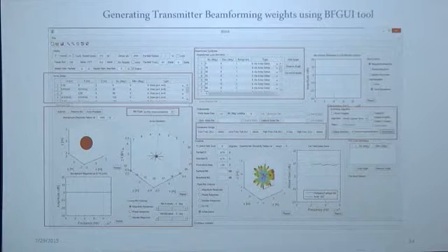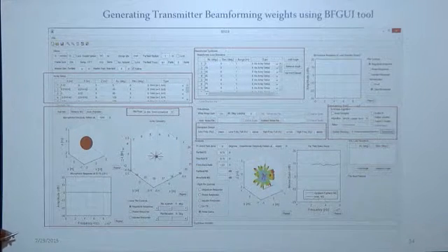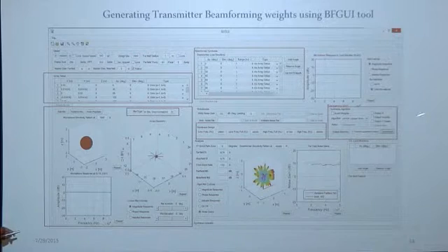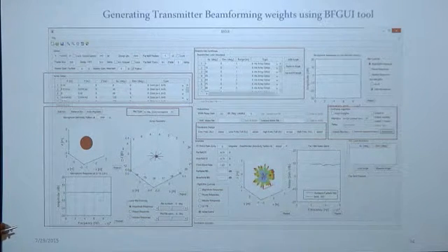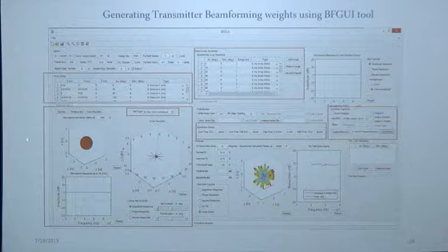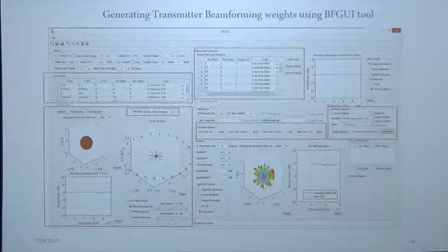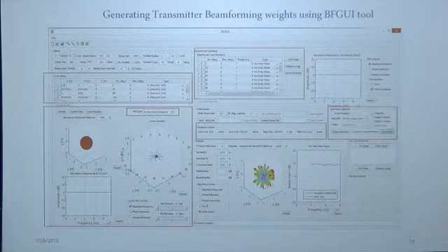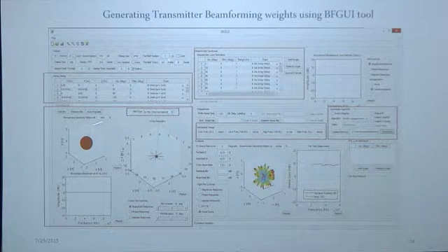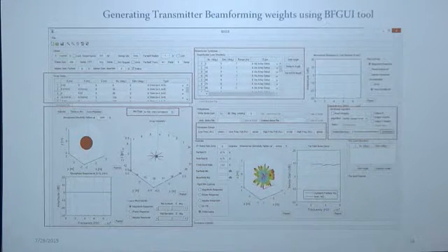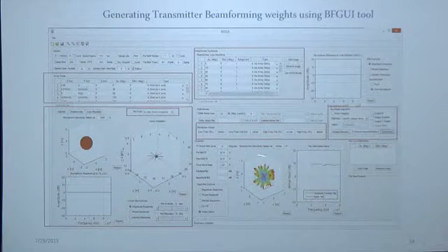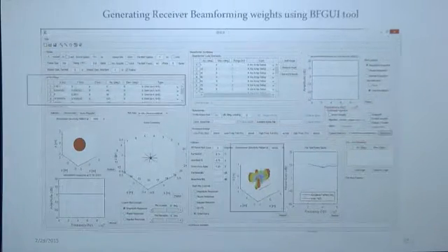This is basically used for generating the beamforming weights. For example, this represents the method we use for beamforming, MVDR closed form, and this basically shows the array setup for our speakers, and this is basically the metadata, the dimensions. So as we can see, the directivity pattern, and this is exported and stored for later use, which we will see.